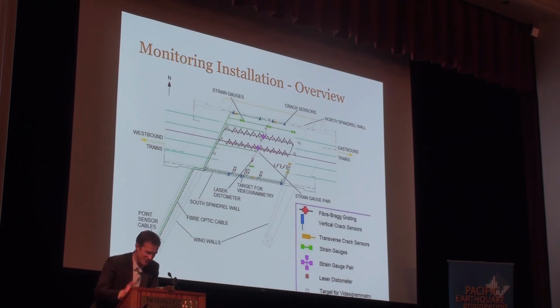So I thought we came up with a reasonably novel idea, although it's used all the time in strain gauges. But we just did basically fiber optic rosettes underneath the bridge to allow us to measure principal direction of stresses and flows, so forces in the structure, by stringing a lot of fiber optic cables. So the triangles is a plan view of the bridge. The two rows of triangles represent the fiber optic system. AECOM, the contractor, put in a lot of other traditional techniques so we could compare and validate the accuracy of our data.